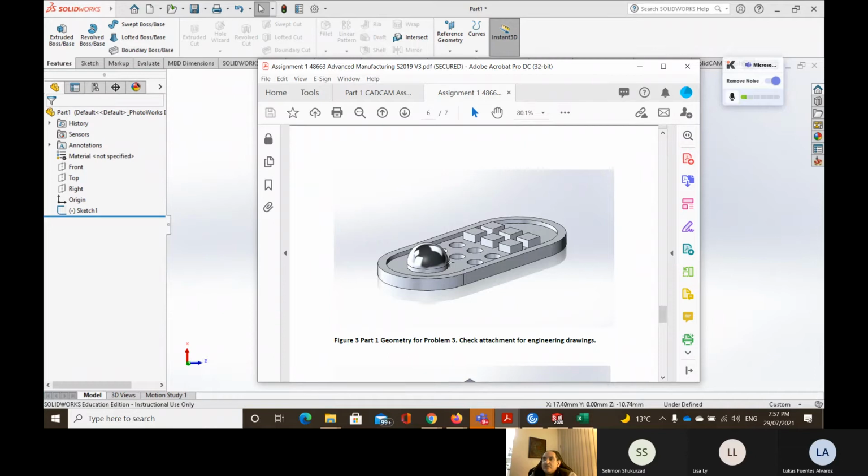It seems to be simple, but it's actually the most complicated because we have a spherical shape at the top. The shape I showed you last time was quite simple because it was flat, so you could find the location of the datum point directly by clicking on the highest level. Here, you cannot do that, so you're going to do another arrangement.